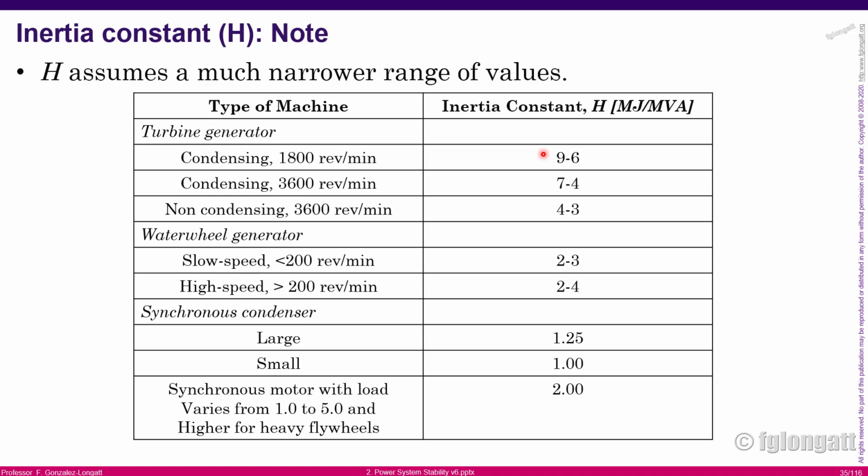However, for any synchronous machine that you are using for studies, please refer to the manufacturer and get the proper information and the proper details about the inertia constant. The inertia constant is extremely important because it defines many of the characteristics of the oscillations in the dynamic process inside the power system. For that reason, be careful when you are including the inertia constant in your future stability studies, okay?